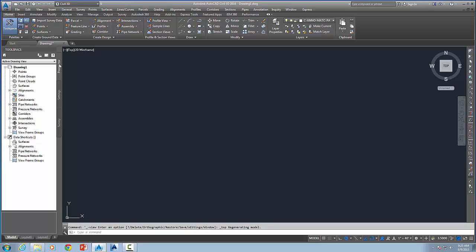And object types in Civil 3D are a lot different than just normal AutoCAD line, arcs, circles, those kind of things. So you're going to have things like point objects and surface type objects, alignment objects. So this is going to be a way that we're going to be working. And so the prospector is really, really important to the whole process. The settings govern the settings of those particular objects. So you notice that you'll have point settings, surface settings, and so we can get to those.